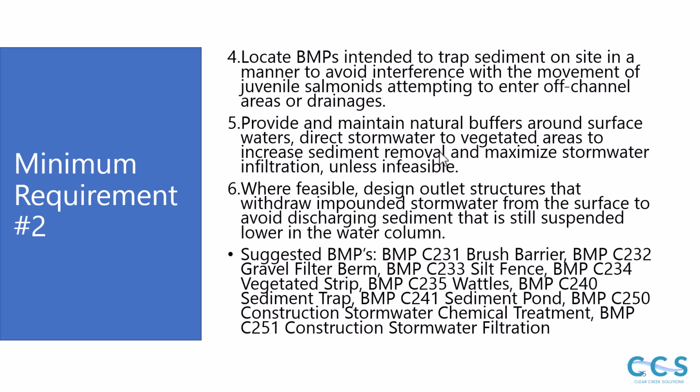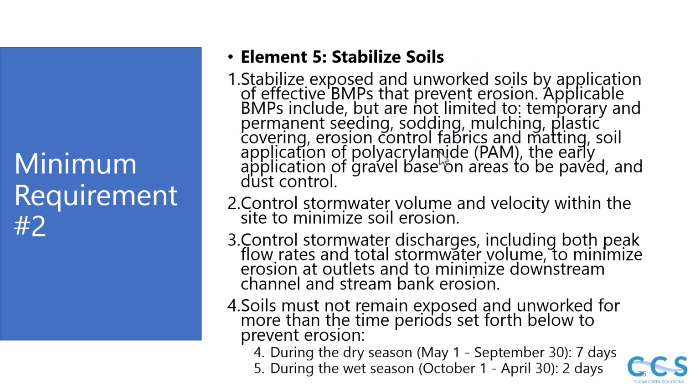Then we want to locate BMPs intended to trap sediment on site in a manner to avoid interference with the movement of juvenile salmonids attempting to enter off-channel areas or drainage. Provide and maintain natural buffers around surface waters, direct stormwater to vegetated areas to increase sediment removal, and maximize stormwater infiltration unless infeasible. And then where feasible, design outlet structures that withdraw impounded stormwater from the surface to avoid discharging sediment that's still suspended lower in the water column, and they have a list of suggested BMPs for that element.